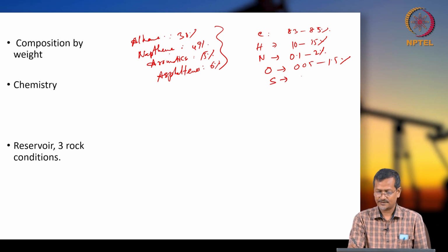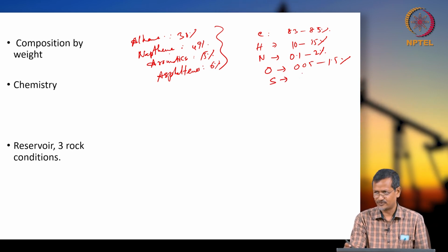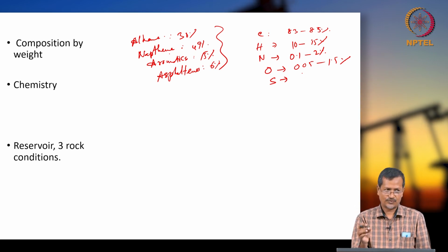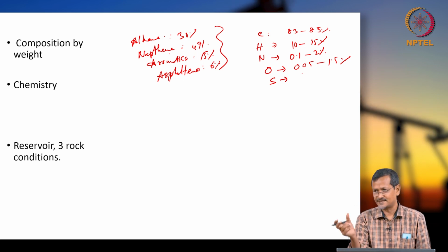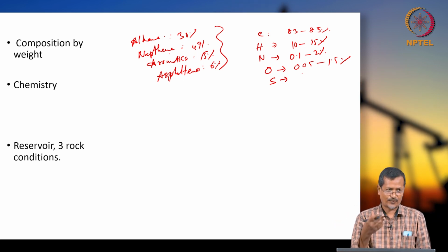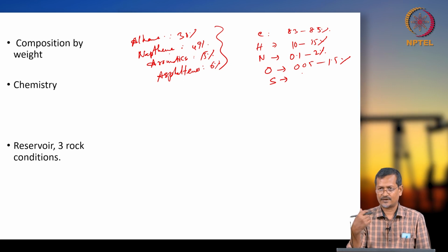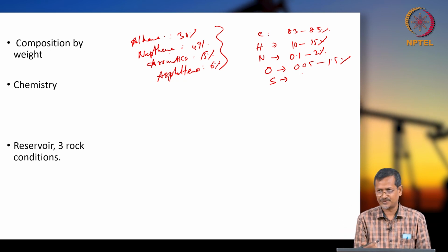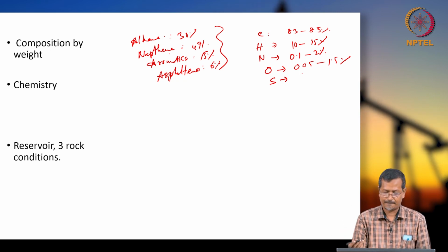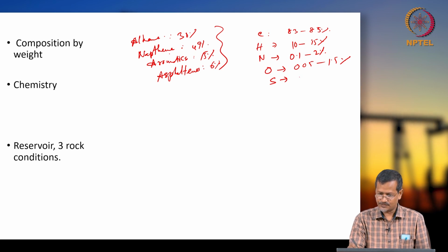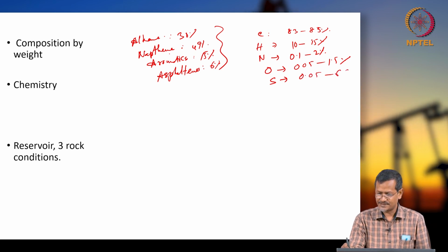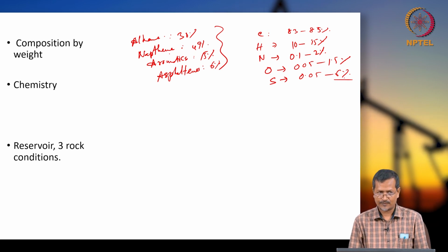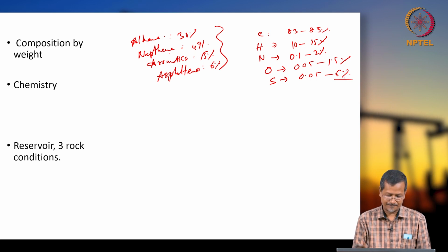Sulfur, this is your enemy actually, hydrogen sulfide or sulfur dioxide. Okay, this will create corrosive gas. Sulfur plus H2 plus water will create acidic gas. So acidic gas means it will be corroding everything, it will be dangerous. So if the sulfur content is higher, you have to first handle the sulfur, then you can do other operations, otherwise all metallic parts will be corroded easily. Okay. So sulfur will be like 0.05 to 6%. So a very high amount is also possible. A small amount maybe they can handle easily, but a high amount you have to treat separately.